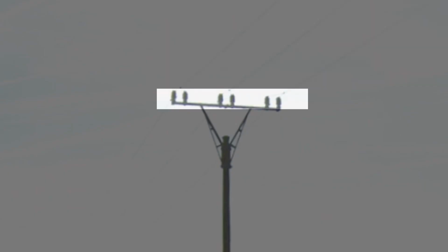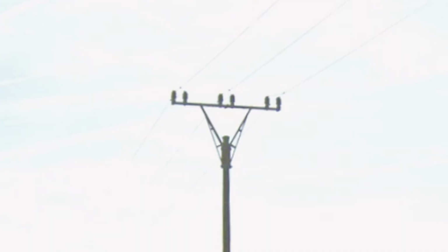These are the conductors. Higher voltage means lower current. And because losses grow with the square of current, higher voltage means significantly lower losses. These are insulators. They separate the conductor from the structure. That allows energy to be transported efficiently over distance. But this isn't just physics. Lower current also means you can use thinner conductors, and that directly reduces cost. It's similar to the difference between 120 volts and 230 volt systems.